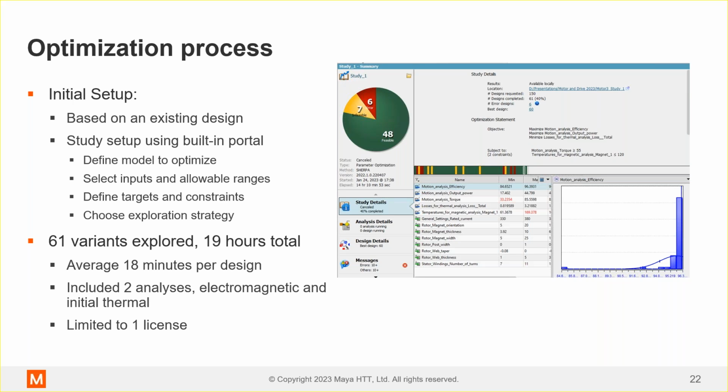Again, HEEDS is an optimization tool. Without a little help, it doesn't necessarily know what's wrong, but when it tries to put the design into MotorSolve, it'll quickly throw an error, and HEEDS can go, okay, that's invalid, we'll just move on to the next. The yellow infeasible designs that we see listed here, those are ones that didn't meet one of our constraints. So the torque was too low, the temperature too high, that sort of thing.